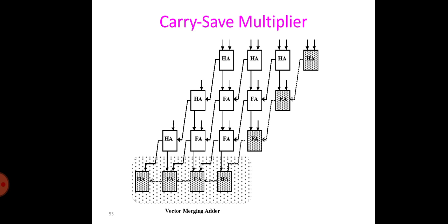While this structure has a slightly increased area cost, it has the advantage that its worst case critical path is shorter and uniquely defined as T mult equals T n plus (n minus 1) times T carry, still assuming that T add is equal to T carry. When mapping the carry save multiplier onto silicon, one has to take into account some other topological considerations. To ease the integration of the multiplier into the rest of the chip, it is advisable to make the outline of the module approximately rectangular. A floor plan for the carry save multiplier that achieves this goal should be rectangular, and you can observe the regularity of the topology, which makes the generation of the structure amenable to automation.